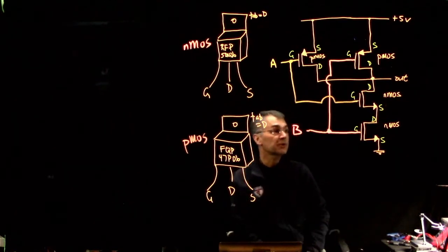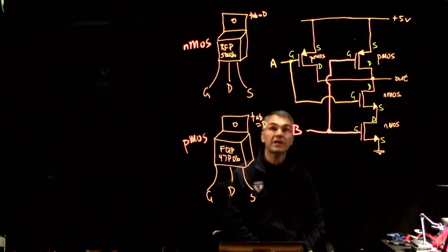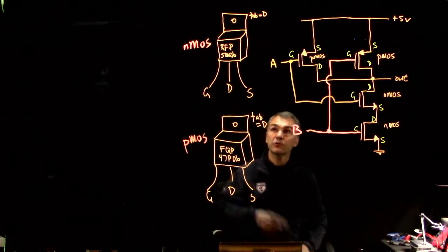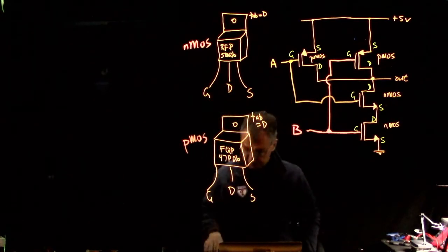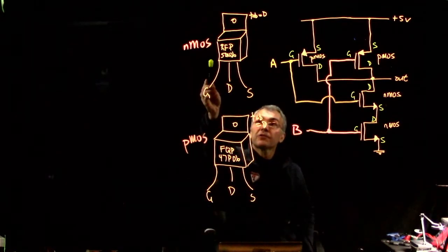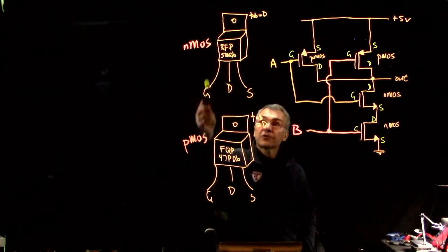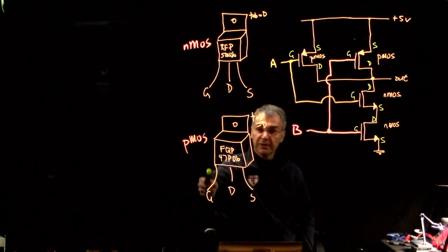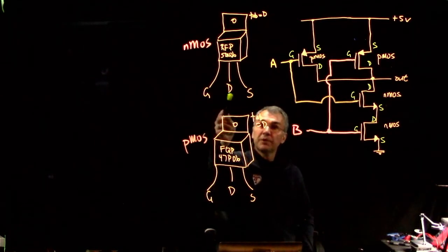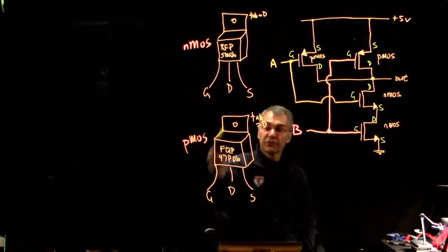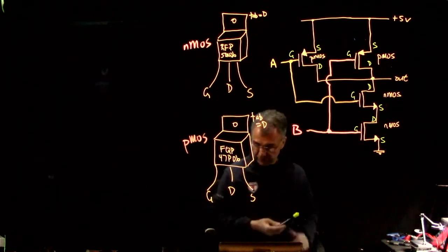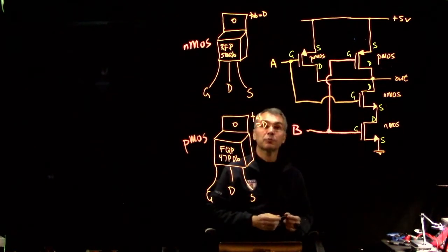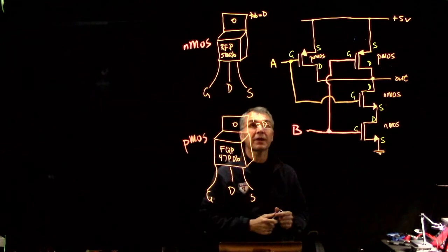So this is building a CMOS NAND gate. So we use 2 of these NMOS FETs, 50N06, and we use 2 of these PMOS FETs, 47P06. They have the same pin assignment, gate, drain, source from left to right if you are looking at the print on the package.